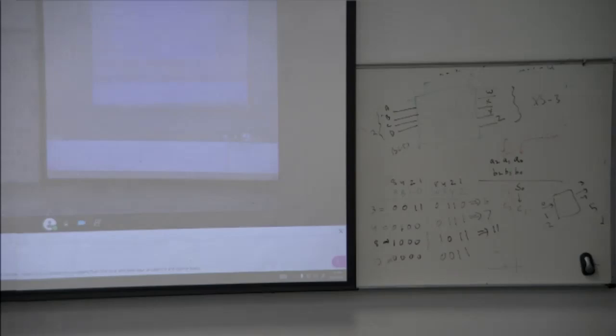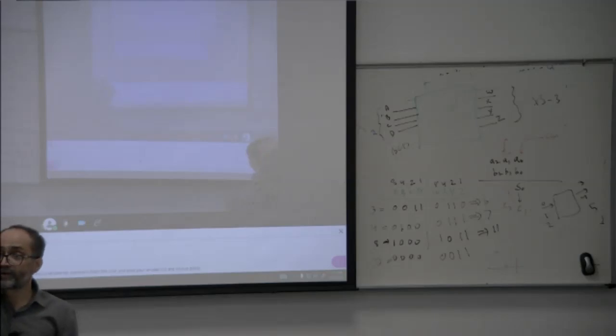Now we did a lot of things. When we want to solve any problem, we design something. What is the first step? Specification. From that specification, then truth table. Then logic minimization. It can be algebraic manipulation or it can be K-map. We derive the reduced expression. After the reduced expression, do what? Logic sharing. After logic sharing, implement on the mapping. It can be AND-OR logic, NAND implementation, NOR implementation, and so on. This is how we should do it.